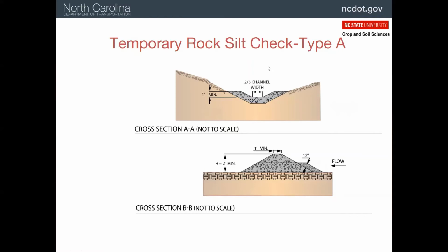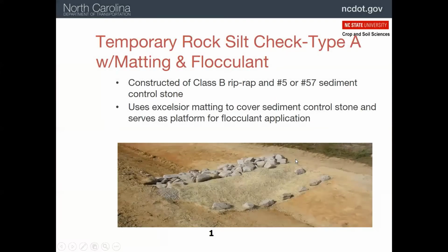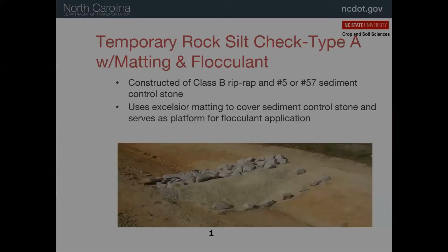Okay, so I had a question about the polyacrylamide, so I'll back up. As far as, well, let's go to this slide. The question was, do you have to apply this during a project more than once? And the answer is yes. You're probably going to need to apply it many times. Every time it rains, every time you have flow, some of the polyacrylamide is going to disappear. So as you're inspecting all these devices, you need to be looking to see if it's there, and if it's not, then you need to add some more. So I hope I answered that question.